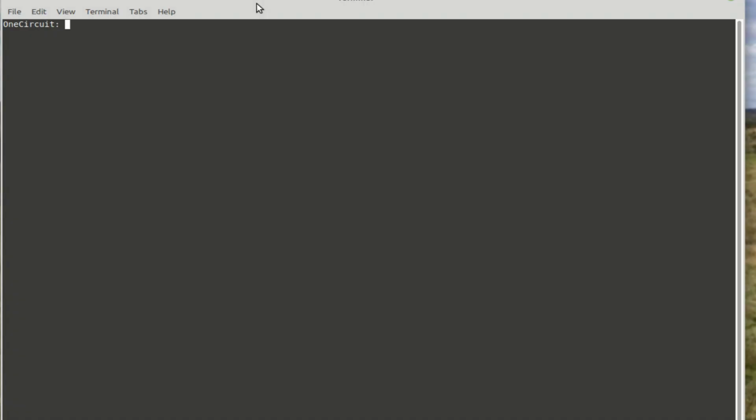Well, with this particular piece of software, you don't have to enter your SSID or your password. You do need to contact your device, however, when you first load up via the serial interface. So I'm using PuTTY to contact it, and I've specified that it's a serial connection. That's where the device is listed, and this is still sitting on the Arduino there. And then the last thing is to say I want a particular baud rate.